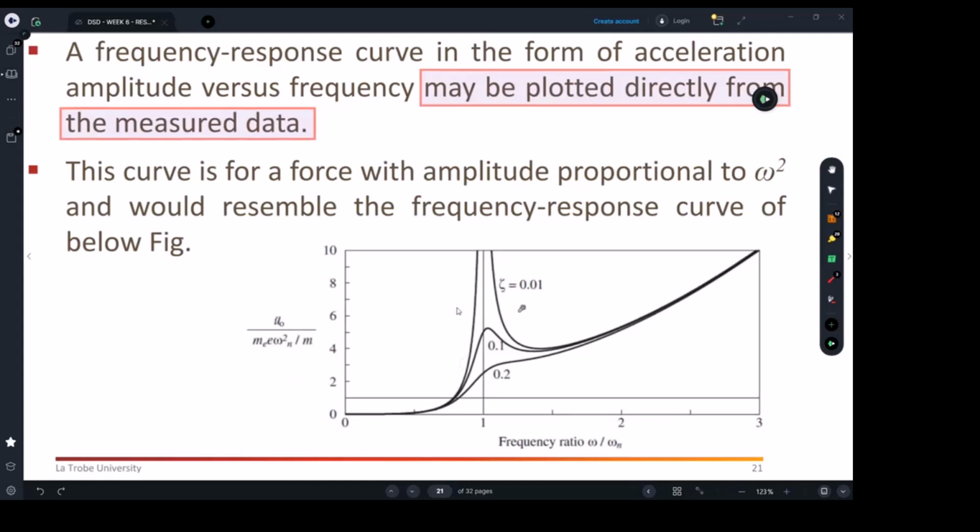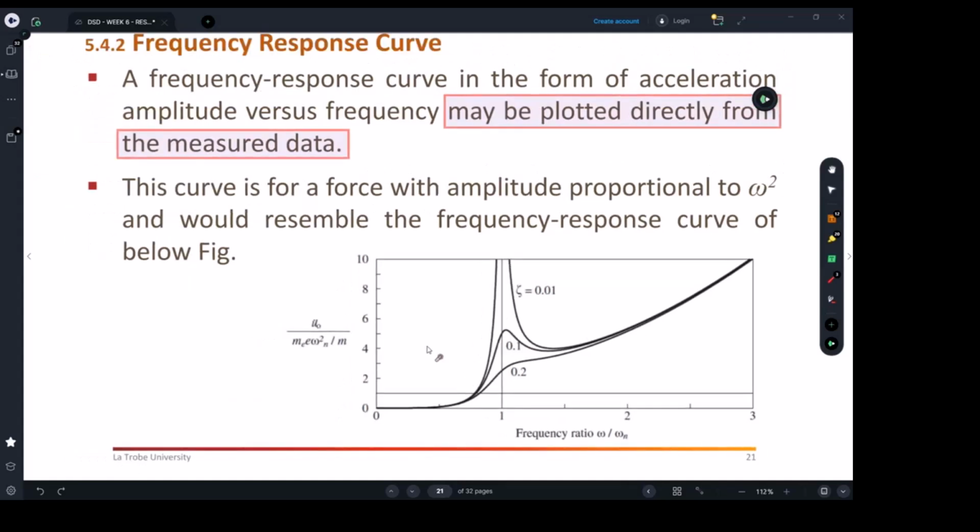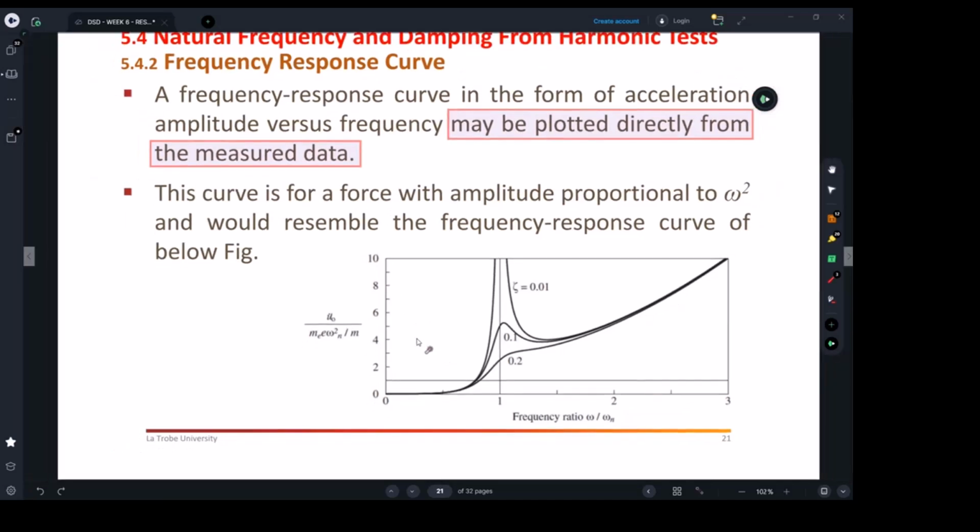And that's it. So once you plot all that, you will be able to work out stiffness. The first thing you can work out is the natural frequency. From natural frequency, you can work the stiffness out. You can work the damping ratio out. You can work many properties that will end up telling you whether that floor is actually working or not. Okay.